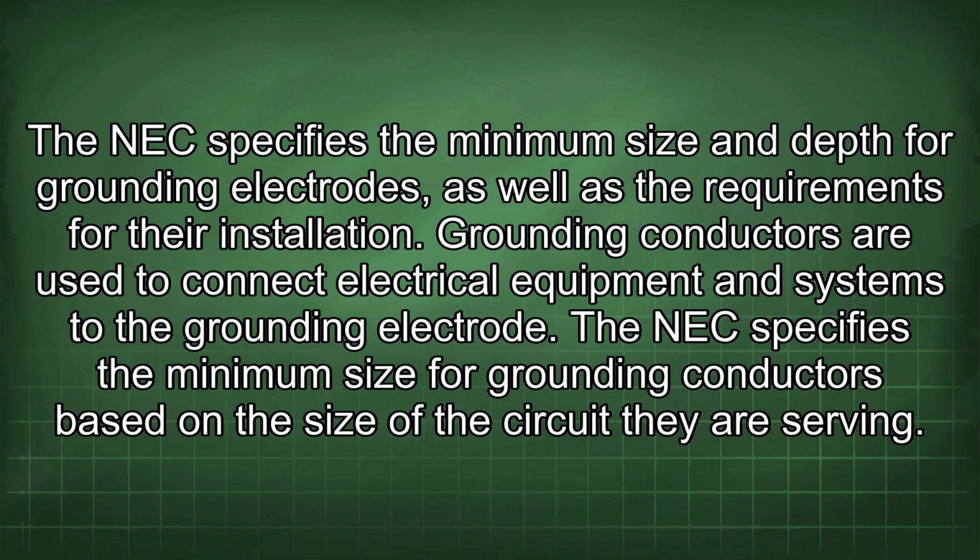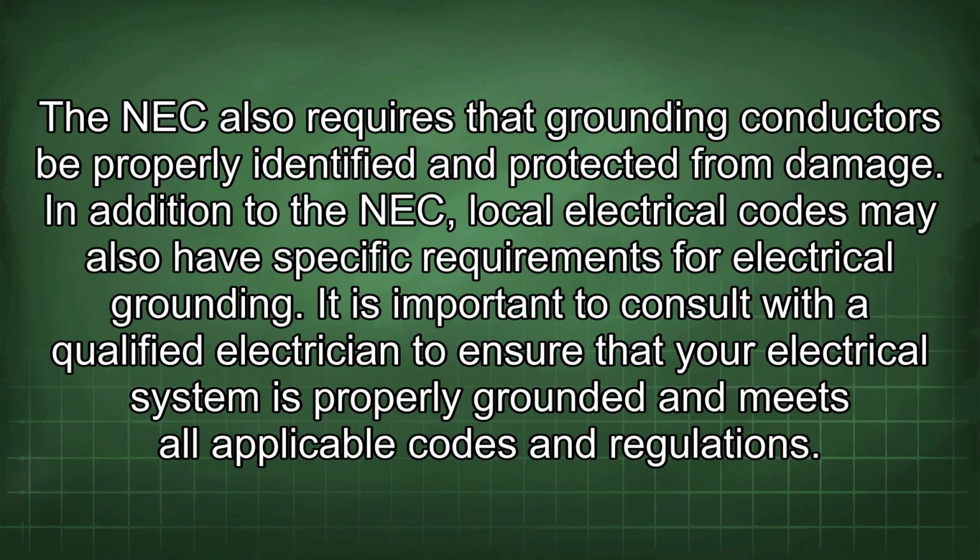The NEC specifies the minimum size for grounding conductors based on the size of the circuit they are serving. The NEC also requires that grounding conductors be properly identified and protected from damage. In addition to the NEC, local electrical codes may also have specific requirements for electrical grounding. It is important to consult with a qualified electrician to ensure that your electrical system is properly grounded and meets all applicable codes and regulations.